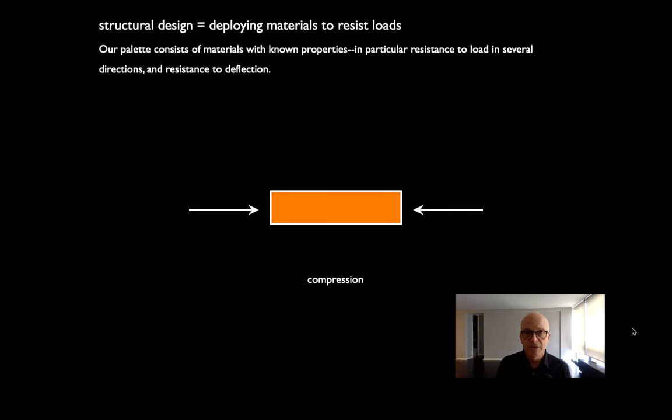The two that we've looked at so far are compression. Materials have a resistance to compression. When we smush them, the particles start to bear on one another, and they have resistance to either changing dimensions or sliding past each other. If we do it exactly the opposite direction, if we pull the material apart, we say that that material goes into tension, right? It's a way that the material has to develop internal stresses that prevent those particles or those fibers, whatever's in there, from sliding past one another or from ripping apart.